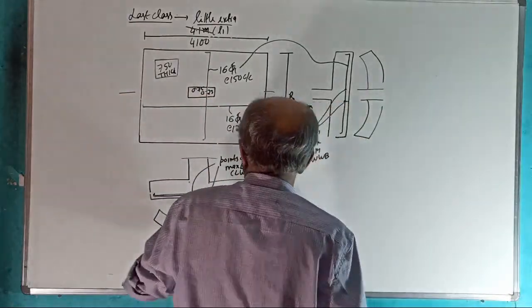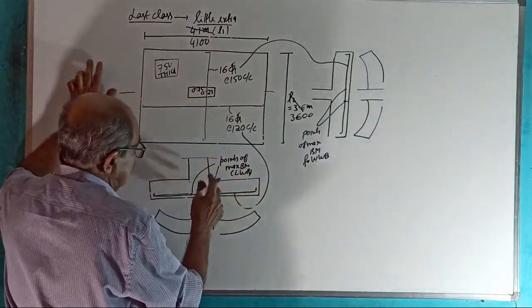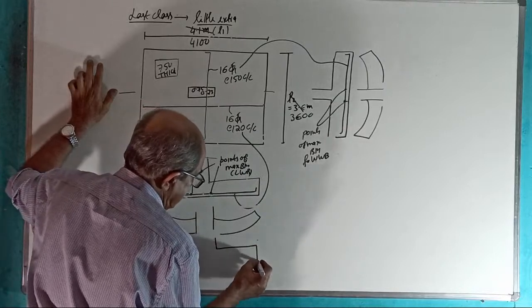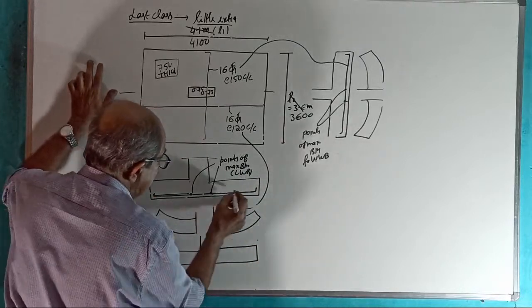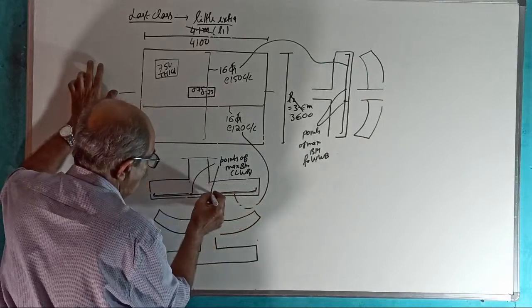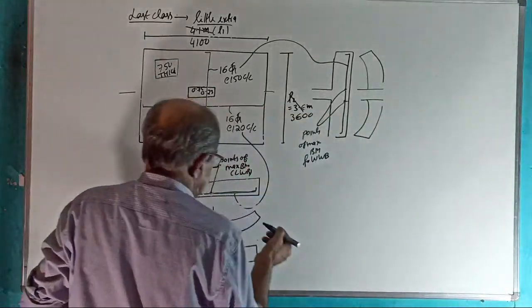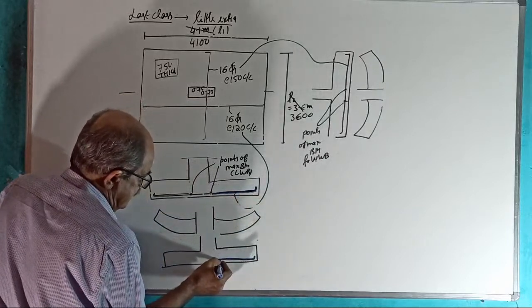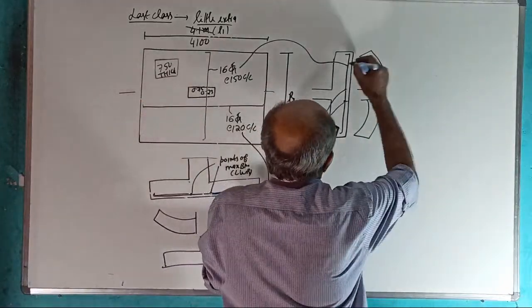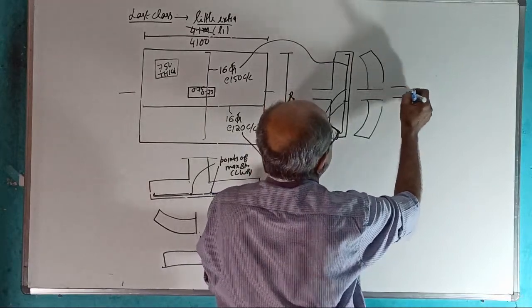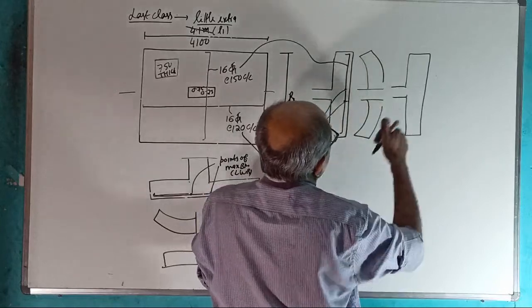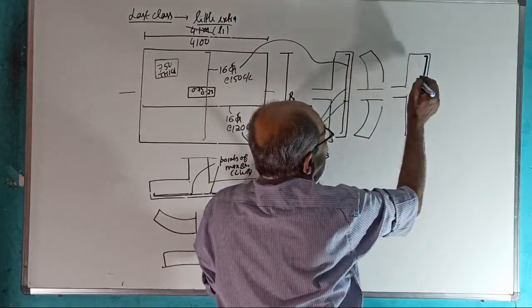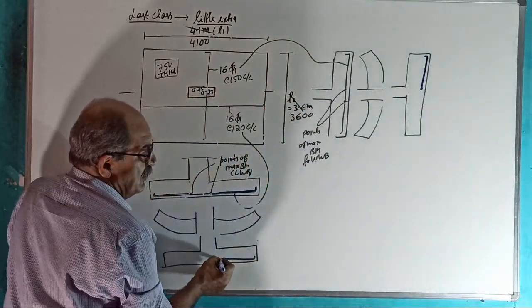Now, C1. Here we got both critical. Now if I consider only one side cantilever, see this bar, only up to here. I'll make it dark color. That bar comes like this. This is the point of maximum BM. Remember, later in ETABS class I will not tell. Here is maximum bending moment. This is the point where bar will have maximum tension.